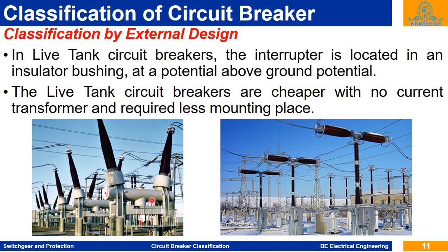From this construction, you can conclude that these live tank circuit breakers are cheaper, with no current transformer. In the dead tank circuit breaker, current transformers are there, and the overall size and space required is more.